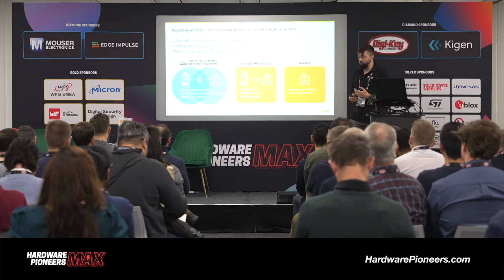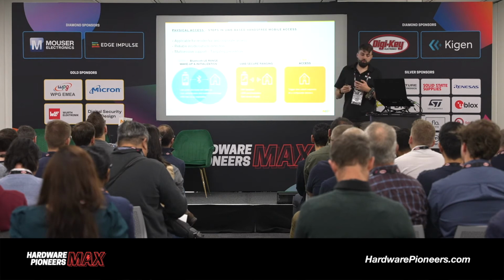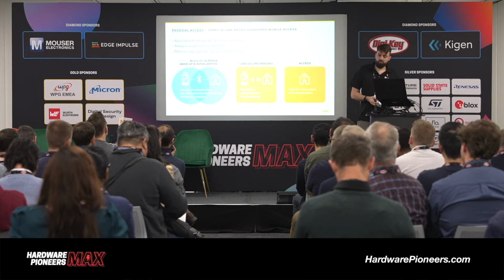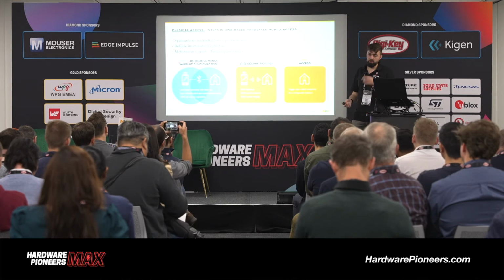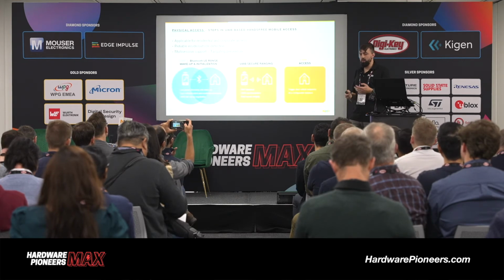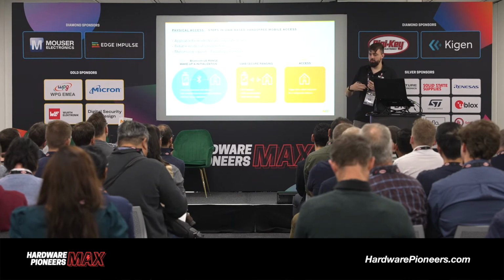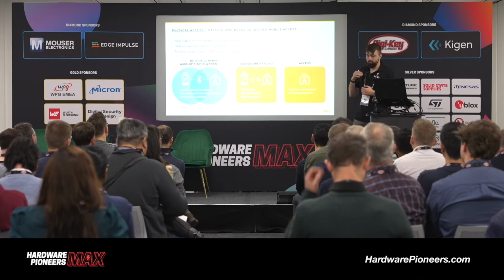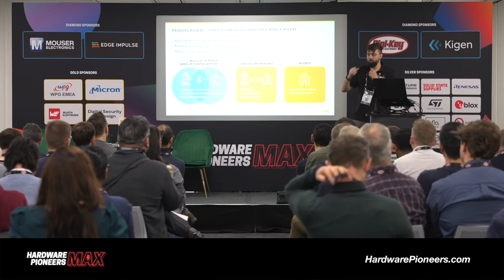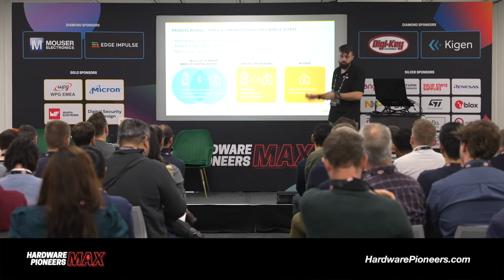The way we do it at the moment is that we use in combination Ultra Wideband and Bluetooth Low Energy. At first, you establish a Bluetooth Low Energy connection between the devices to exchange information, keys, ranging parameters, and then you use Ultra Wideband to measure the distance between the devices and enable the handover and open whatever you want to open.